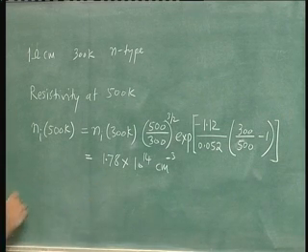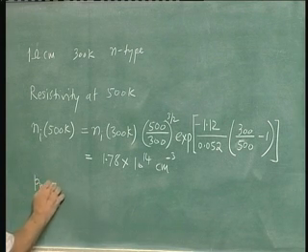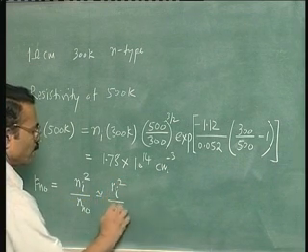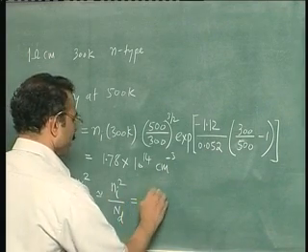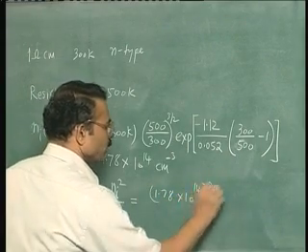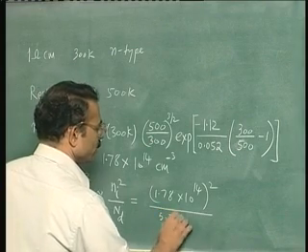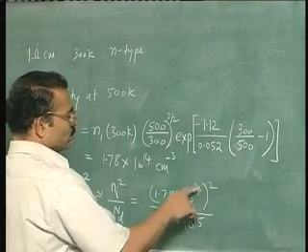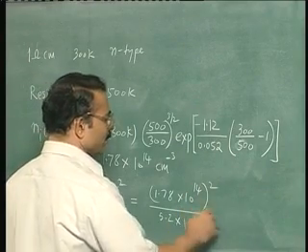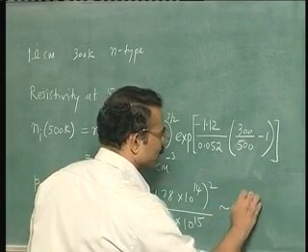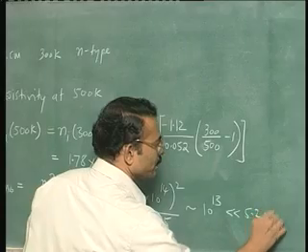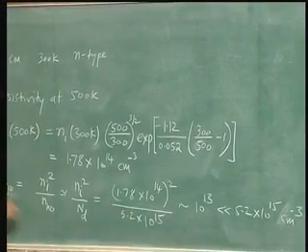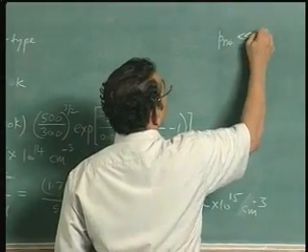Okay. Now the minority carrier concentration, that is pn0, is equal to Ni square by Nn0, which is Ni square upon the doping. So it will be equal to 1.78 into 10 power 14 square upon the doping 5.2 into 10 power 15, and evidently since this is 10 power 28 and this is 10 power 15, the order of this particular result will be 10 power 13. So this is of the order of 10 power 13, which is much less than 5.2 into 10 power 15 per centimeter cube. Okay. So what we find is pn0 is much less than Nn0.